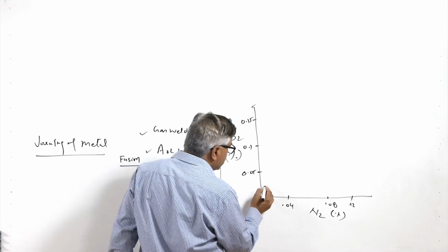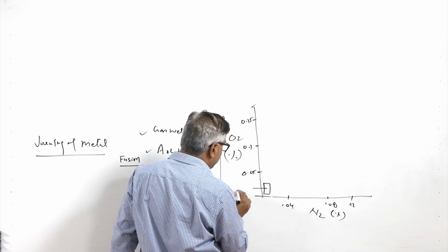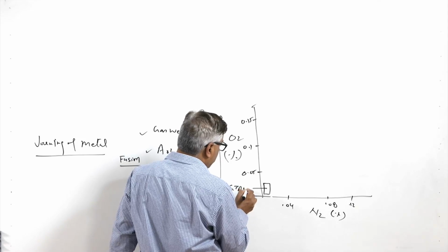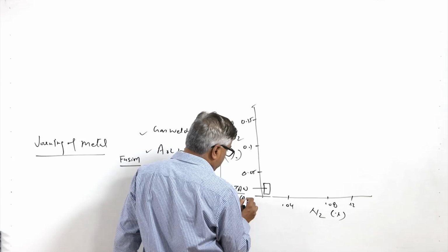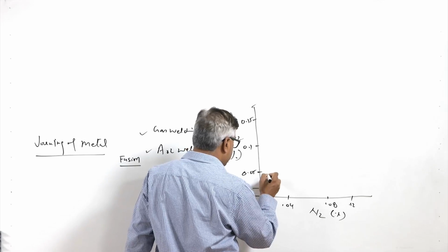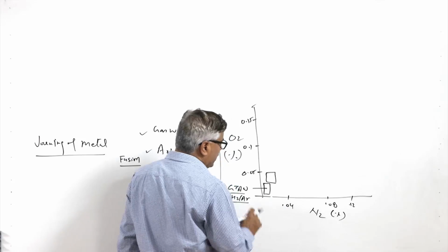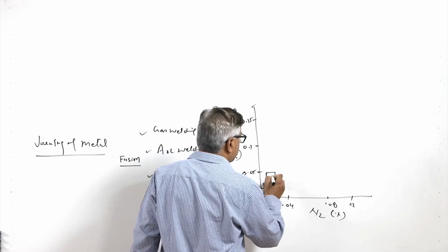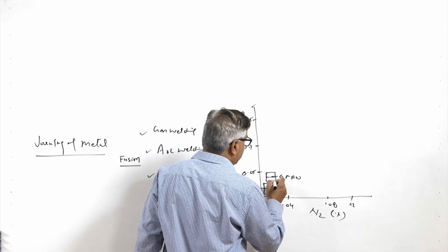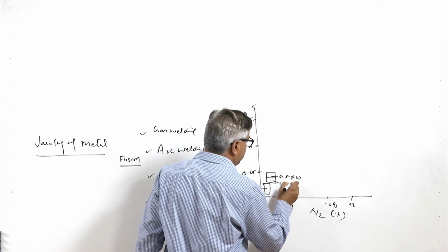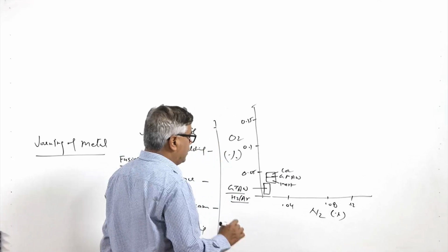With regard to this, the cleanest weld is produced by the TIG welding process, GTAW, when we are using helium or argon, but somewhat more oxygen and somewhat more nitrogen is produced when GMAW uses inert gas. It results in somewhat lower oxygen, and with CO2 more oxygen is produced in the weld.